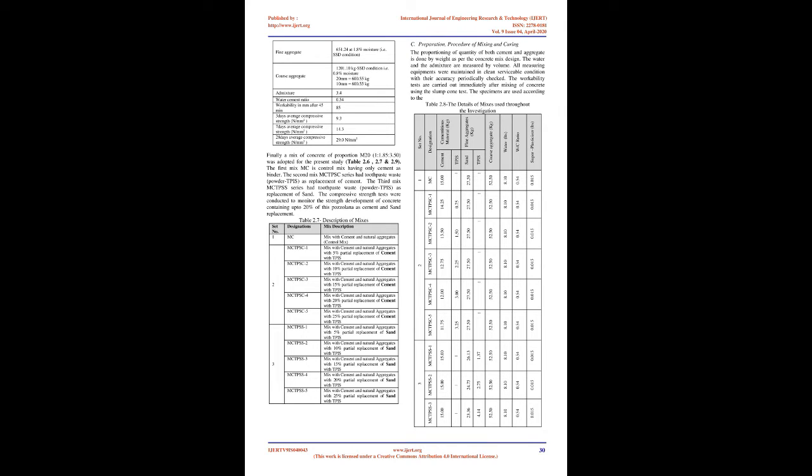Few studies have been performed on utilizing sludge materials in the process of concrete making. Petro et al., 2013, conducted an experimental study for the innovative use of hypo-sludge in concrete formulations as a supplementary cementitious material, tested as an alternative to traditional concrete. The cement has been replaced by waste paper sludge in the range of 0%, without hypo-sludge, 10%, 20%, 30% and 40% by weight for M25 and M40 mix.